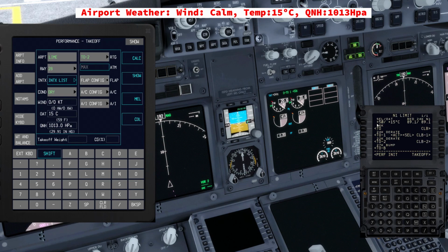In that case, the engine is gonna give us a takeoff thrust that is lower than the 24k. So in this case, it's gonna have 24k with an assumed temperature of 50 degrees, because 50 degrees is a higher temperature, and the engine is gonna give us less thrust because it's trying to protect the engine from a high EGT scenario, and on top of that, it's trying to get the correct air and fuel mixture, okay? And that's how the assumed temperature method works.